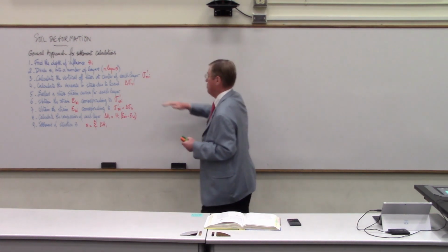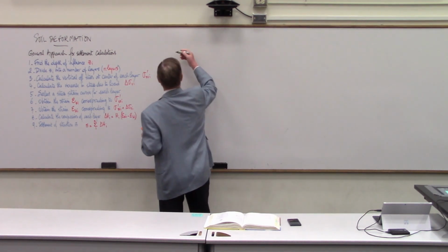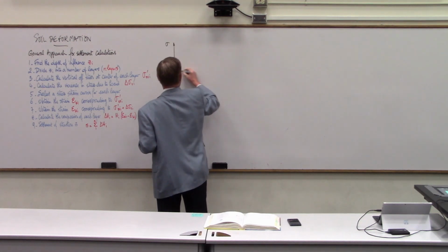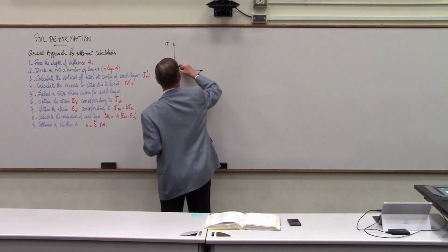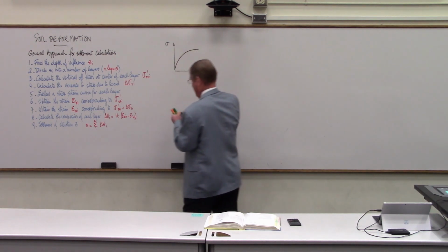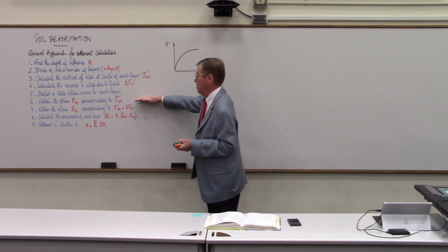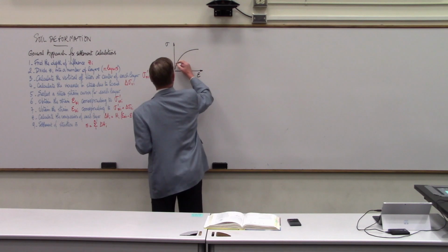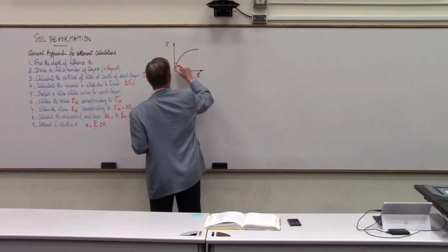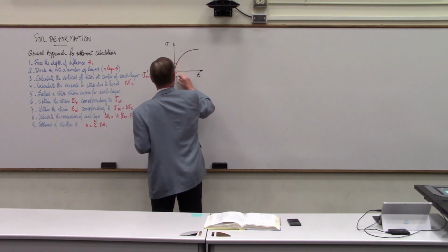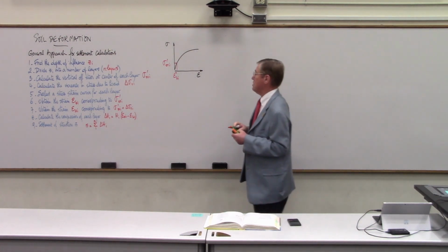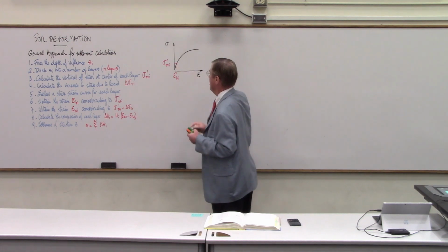Because remember, what we're going to be using that stress strain curve for is that it's going to say stress right here, and then it's going to say strain right here. And you're going to get a certain stress strain curve. And then it's going to say obtain epsilon B I corresponding to sigma prime 0 VI. So you're going to go here at sigma prime 0 VI, and you're going to read the corresponding value, which will be the strain before the loading takes place in the center of layer I.